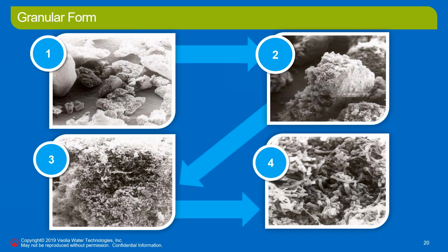So let's take another look at some close-up pictures here. In picture number 1, it's a broken granule in the center. It's just been pulled apart, and if you go in a little closer microscopically to number 2, the broken granule looks to me like a hunk of bread with some fibers in it. And if you go in a little closer, it is quite fibrous looking, and I think that comes from the methane formers wrapped around some of these acid forming rods.